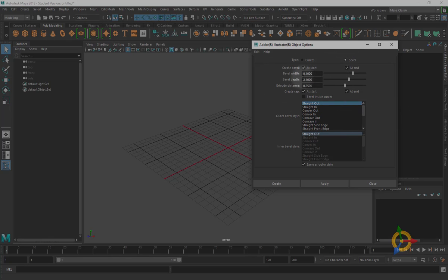Okay, so basically what we have here is it'll create a three-dimensional object with an angled beveled edge around it. Okay, and that's what these bevel settings here are. If you turn these two off, what you get is just a flat sort of front and back on your text. It'll still be three-dimensional. It'll have a thickness which is controlled by the extrude distance. So the higher you make this number, the thicker the letters get, or the objects get, and it's based on the grid size. So if you set this to 1, the object or the text will come out as thick as one of these grid spaces. Okay, so I might just set that to 1 anyway, to make the text a bit thicker.